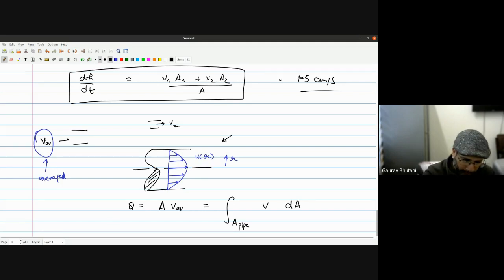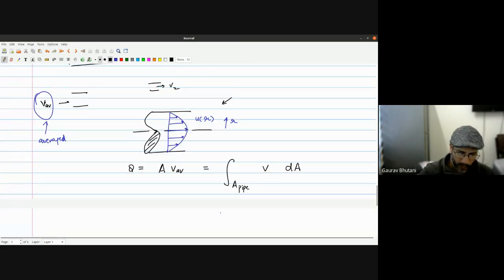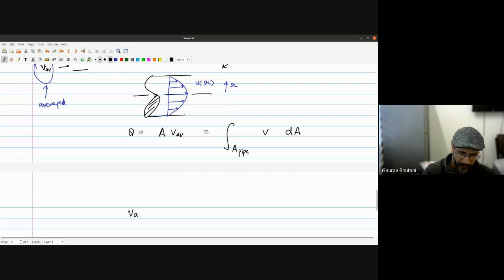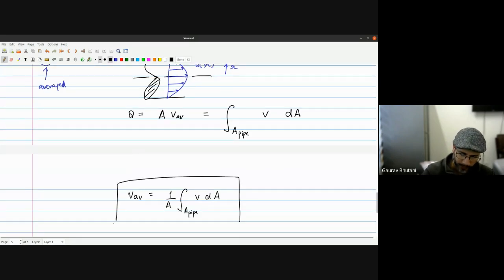Okay, so just remember this, that whatever average velocities you talk about in the inlet and outlets is actually calculated. If it's given in the problem, then that will actually be an area averaged. So if you were setting up your own problem, hypothetically, then you'll have to supply the average velocity values by using this idea.